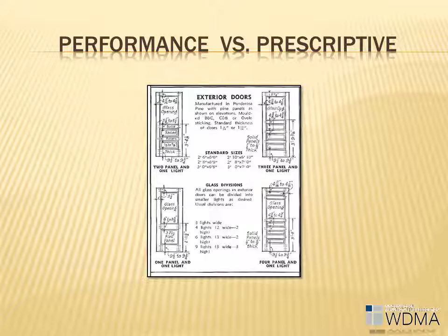The significance to the specifier has to do with the emphasis on performance rather than reliance on prescriptive design specifications. Older standards told manufacturers what materials to use and what dimensions each component needed to be. The result was a functional door, but also a product that could not take advantage of innovative assembly or materials. Results also meant that some doors were required to overutilize scarce or dwindling sustainable materials such as certified wood, hiding most of the volume of these resources inside door assembly.